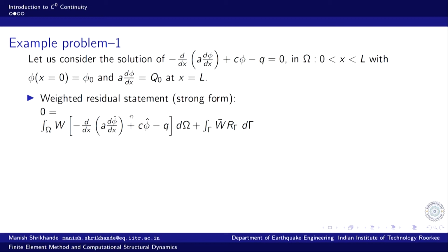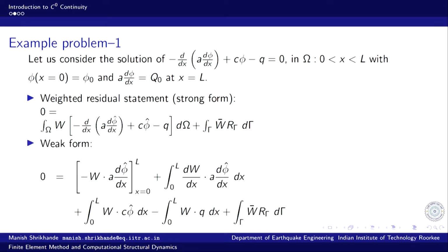This first term is the weighted statement of the domain residual, and this is the boundary residual term. I am not expanding on the boundary residual term at the moment. We will be concentrating on the domain residual term for development of the finite element approximation. If we develop the weak form of the weighted residual statement from this expression, it is just one step of integration by parts of this first term.